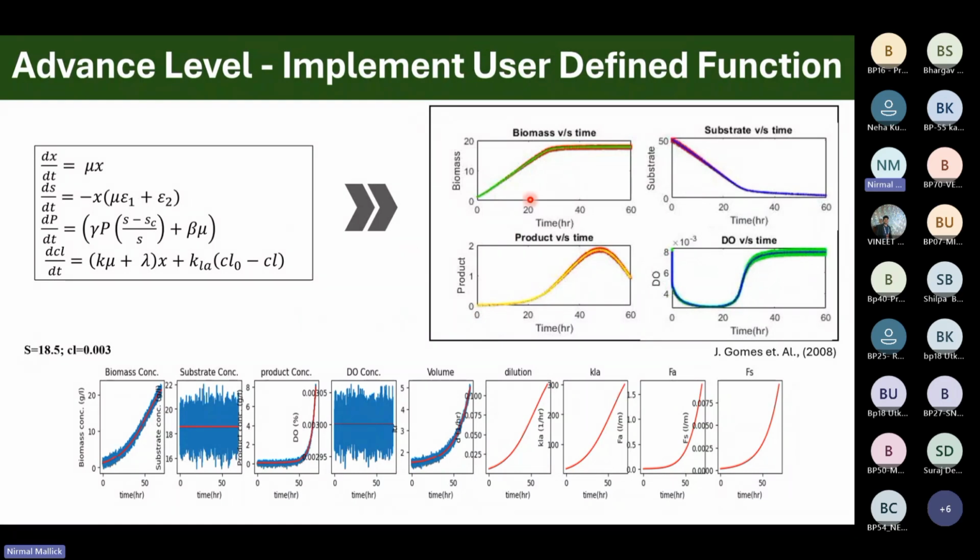When you integrate this with the bioreactor using user-defined functions, then you will have the cells growing inside the reactor as a digital twin of a bioreactor, right? So you can approach it by changing the substrate concentration and the aeration rate, and having a lot of contours, and then find an optimized region to operate, and then you can have a model for this, right?